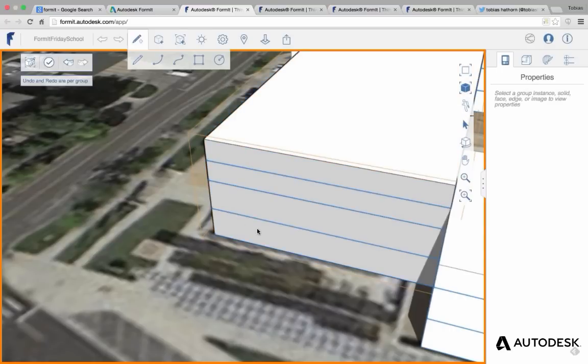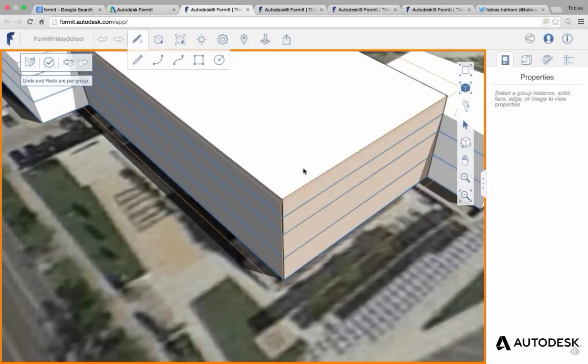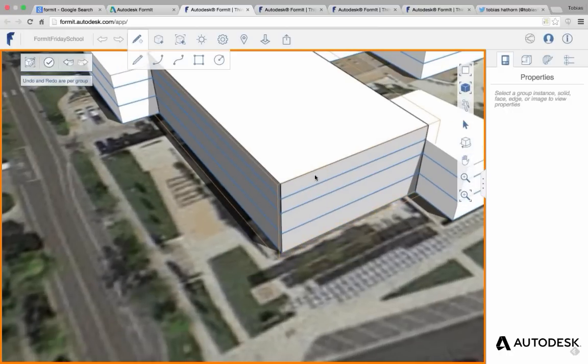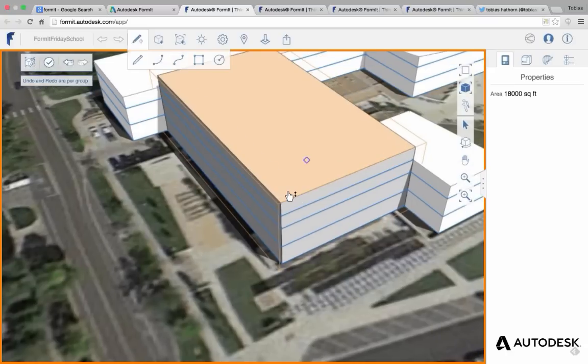I like that edge select tip. I never knew that selecting an edge gives you the length of that edge. Yeah, it's a pretty handy little feature. And you need to be on the properties pane in order to see it, but it's pretty nice. Also, if you select a face, you can get the area of just that face in the properties. So if you wanted to know the area of just that one piece, you can get it that way.